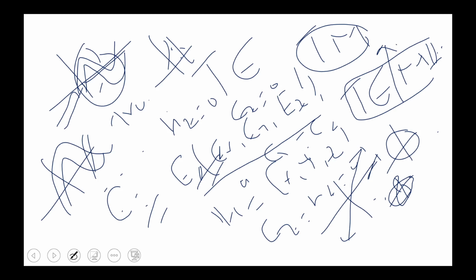Okay. Also, we discussed the modulator last time. We said we modulate two complex data streams onto the LP01X and its degenerate mode LP01Y. Those are the two polarization multiplex modes. And in the LP01 mode, that is the mode profile, right? That is traveling as a sinusoid and then we will encode data in the in-phase and quadrature components.